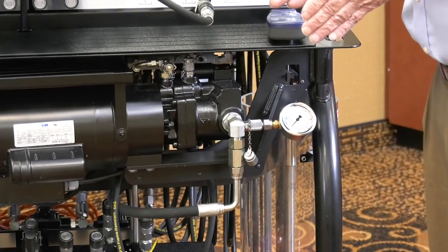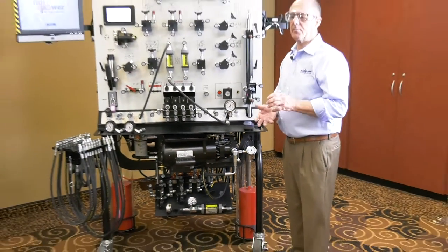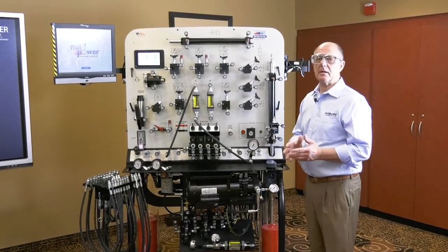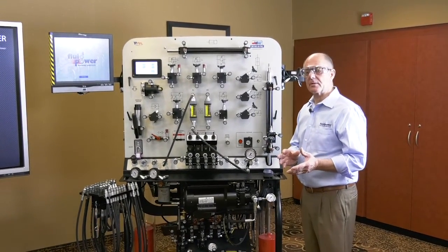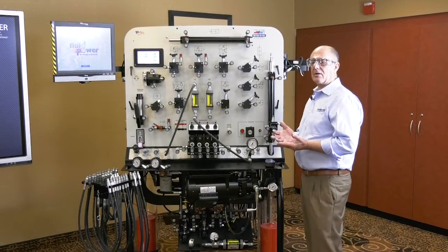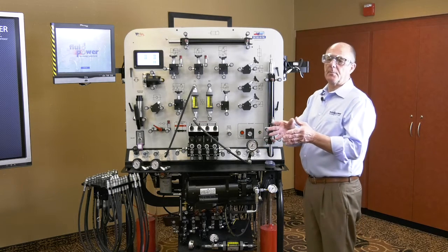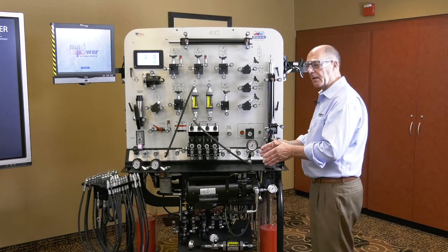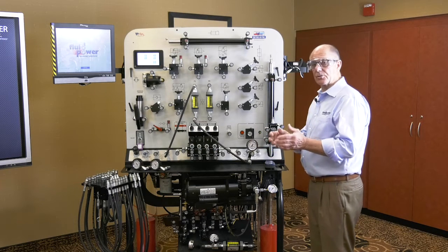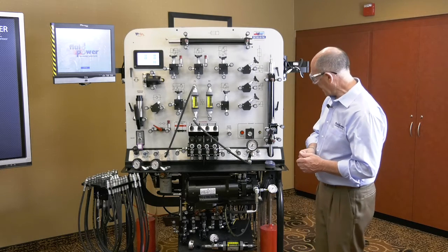Some things as simple as screens in reservoirs, a breather on top of a reservoir, an RPM change if it's a variable speed drive, an overspeed condition. Well, if some normal situation like a breather plugging or a screen plugging can affect a pump's inlet restriction, then surely we must monitor that on a proactive maintenance basis.